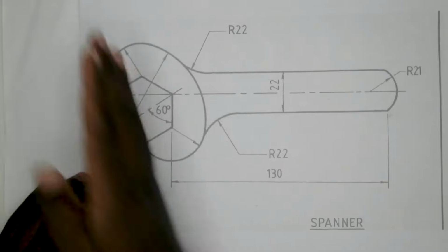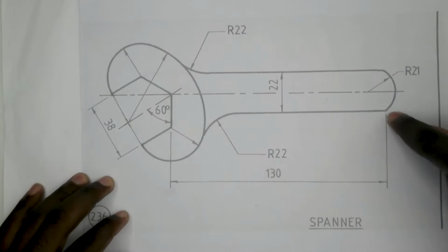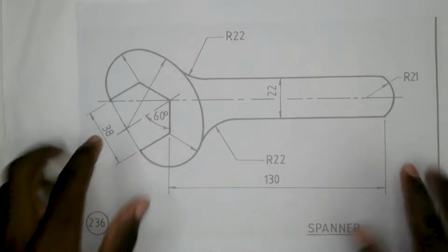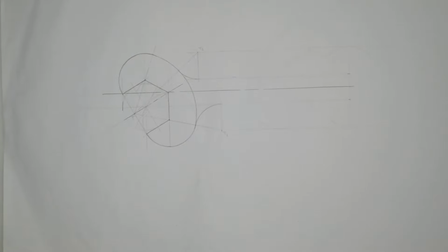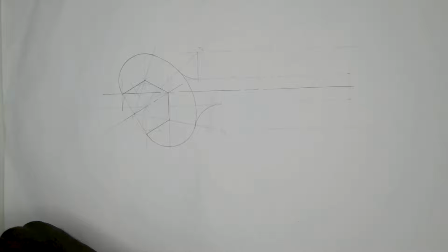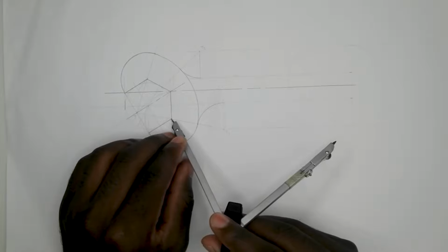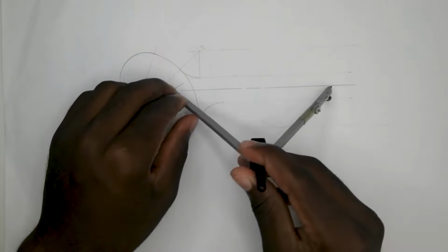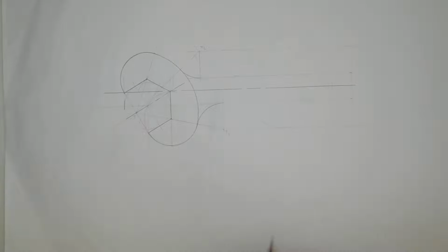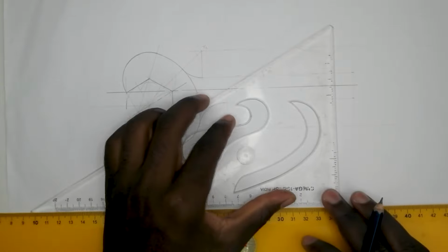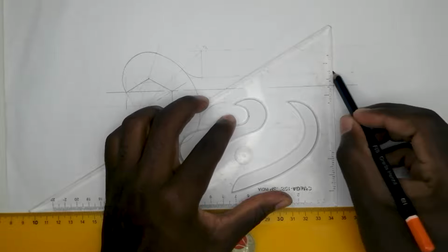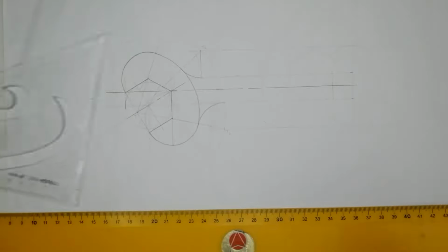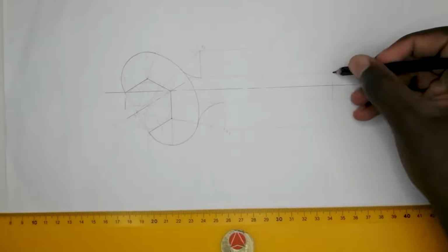You can see we are progressing from this part to this part. Now let's locate this end point, which is 130 from this side. To do that, we can use our compass, measure a distance of 130. Remember, we're working in millimeters, so that is the same as 13 centimeters. The easiest is looking at a line that we have that goes all the way. We can measure from the center line here, like that. It can be a good idea for us to mark this part with a straight line so that it's even more visible, like that. I'm using a construction line. So we've got this point here and this point.